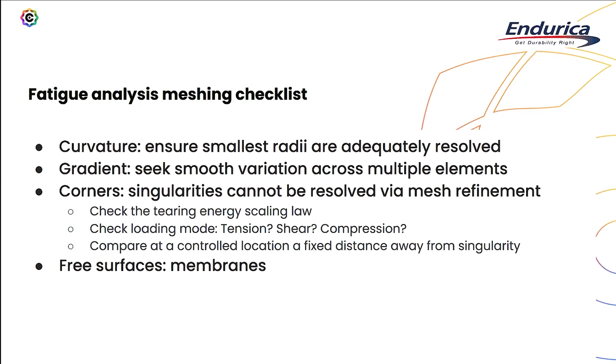The reason we do that is the membrane elements do a great job of capturing the plane stress condition. If you look at where cracks initiate, it's more common for cracks to initiate on free surfaces than on the interior of a part. So when we pave with membranes, we're ensuring that we accurately represent the plane stress condition on the surface of the part.